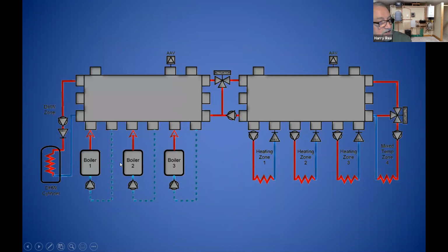Again, here's another scenario. You have 3 boilers on one side, the mixing valve. Remember, the chambers matter. So when you're pulling the water down, you can reverse the flow on what I class as a flow pipe here, it can become a return, because your imagination is going to guide you to say, you're pulling from the bottom chamber, and the second connection, the 4th and the 6th here, connect from the bottom chamber, and they're delivering up through the pipes to the top chamber, and the top chamber can feed the hot water, and the top chamber can feed the mixing valve with the pump circulating.